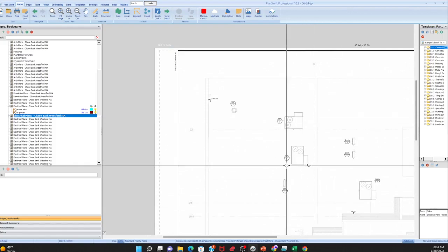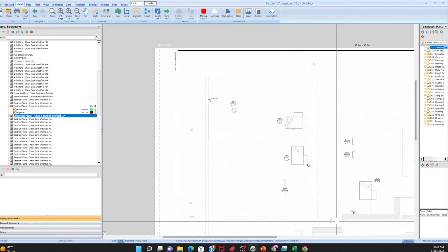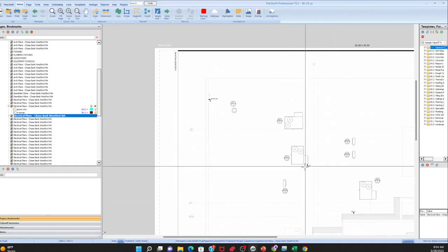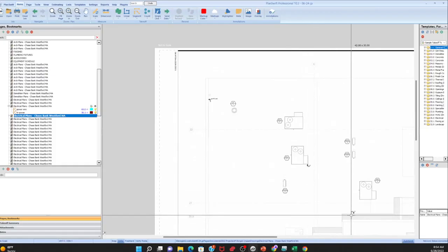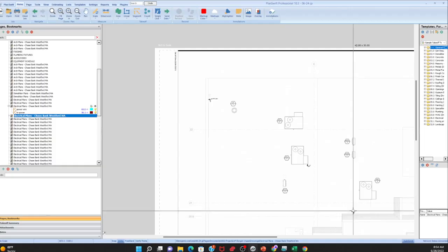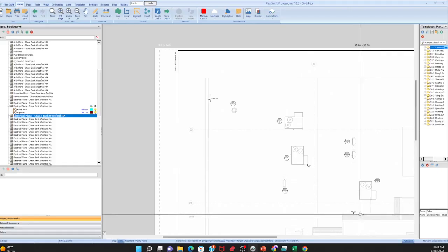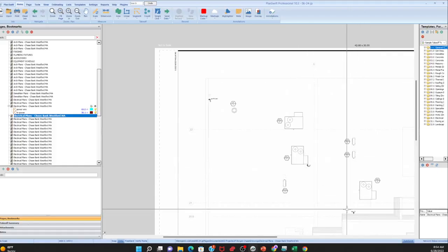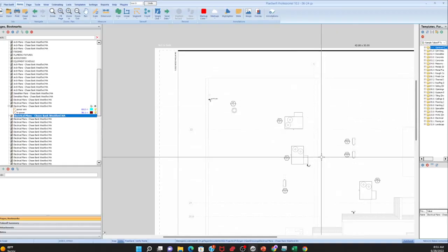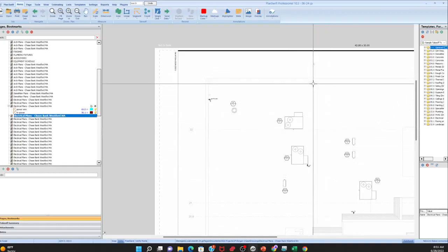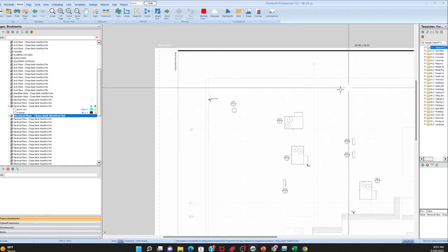So when it comes to a rooftop unit, what conduit are you going to use? Rigid steel? Is it going to be PVC? I don't know. We just want to get a good measurement, and your electrician can tell you the type of conduit we're going to use, but it's still going to be number 12 wires unless it says something different. And then we've got to get these all together, and we're going to assume, where was that panel? Somewhere at the end of the building over here. So we've got to just run it.